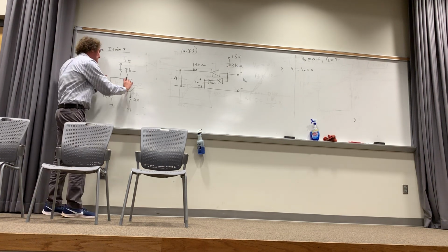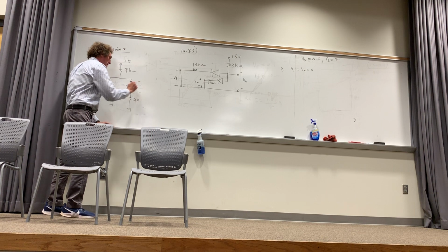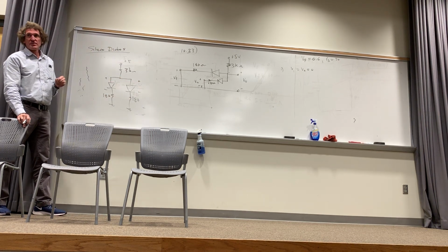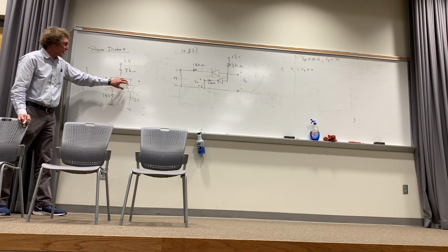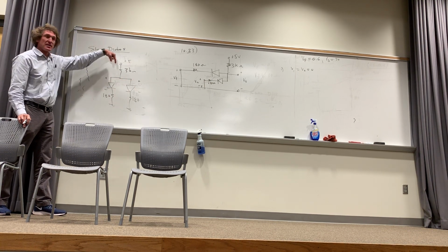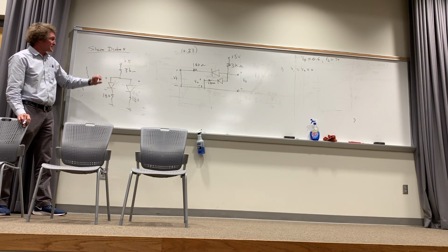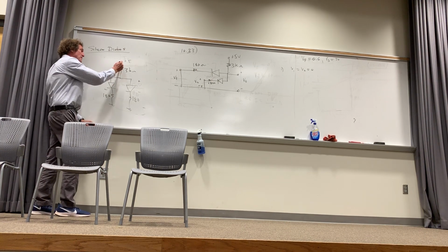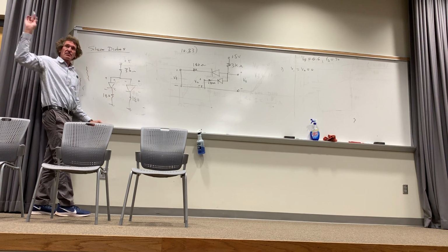If you remove both of these diodes, what voltage do you develop here? Just remove them. What would you get? How much current would flow? Answer that. If you cut these diodes out, how much current would flow right there? None, right? Y'all with me? If you pull these out, no current would flow, right? If no current flows, that means that 5 volts would have to be developed there and there, right? How many see what I'm talking about right here?